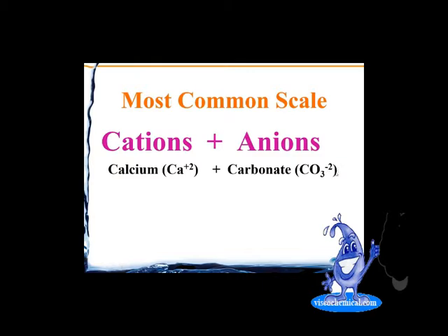So we have CO2 that's in the atmosphere, but most of that CO2 in the atmosphere dissolves in our surface water. So we're 70% covered with water. So the CO2 dissolves in water, and then we'll see here in just a few seconds the relationship between pH and CO2. So the carbonate came from CO2 because the pH was above 5.5. So all we have to do is drop the pH down, and we're going to turn that carbonate back into CO2, in which case we're going to see a lot of tiny, tiny little bubbles in our cleaning tank.